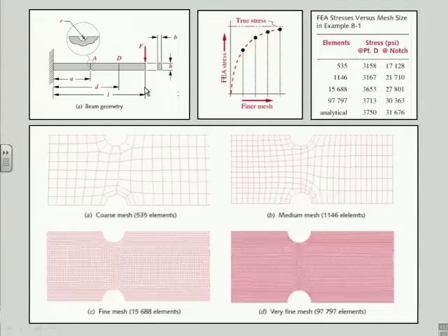Yes, sir? I took Professor Wu's class in this class. Whose class? Professor Wu's class. Yeah. Also, for a situation like that, you can exploit the symmetry of the part itself. Yeah, absolutely. So you can constrain two sides that are inside the part, and then the numbers it returns are just as valid. That's correct.